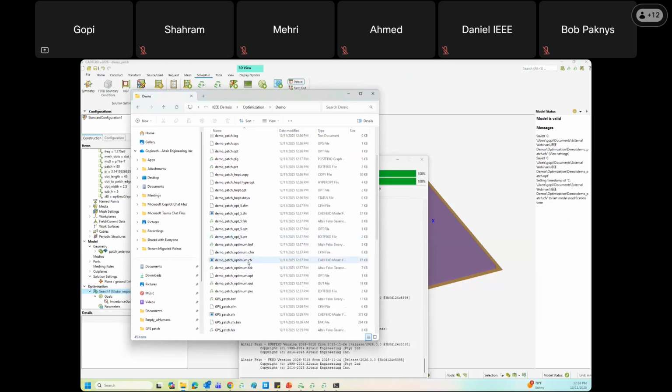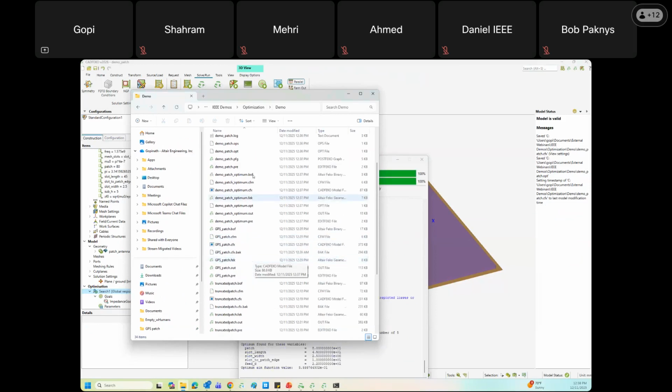That way, if you start a global optimizer and run it for a few iterations, let's say 20 iterations, you can find the best of those 20 iterations under the optimum. You can give this as a start value for a local optimizer, and then the local optimizer can quickly converge to the global minima. So that is a workaround I always follow to make sure I'm not running the optimization for too many iterations, trying to get the optimal solution in a few iterations by mixing the global and local optimizers.